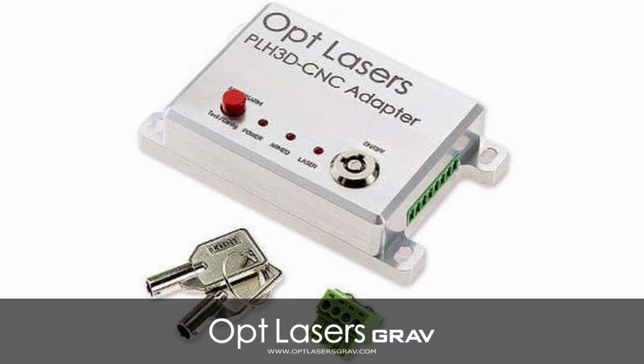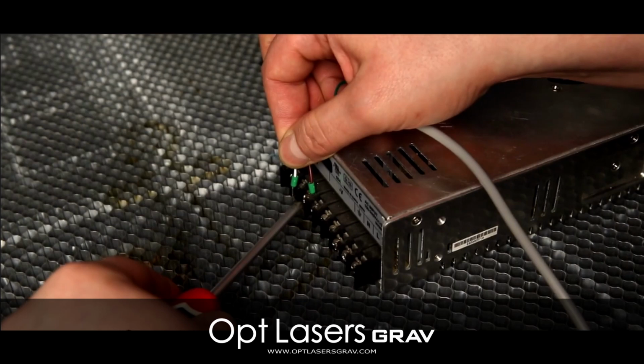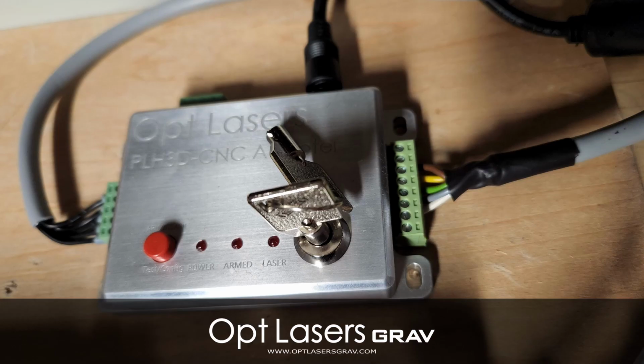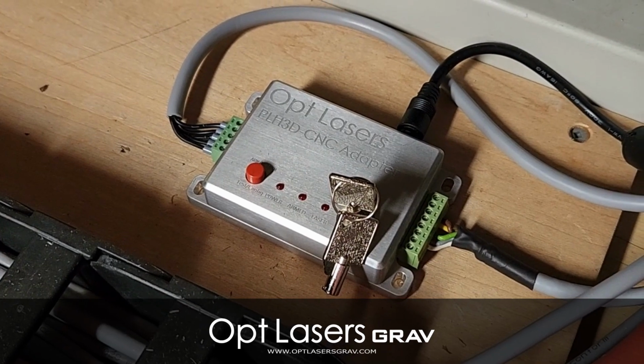Next, let's find the CNC adapter and get that installed. Every laser upgrade kit should come with a CNC adapter. You can choose not to use the CNC adapter or the safety features that are incorporated into this unit. The laser head gives you the option of direct integration. The wiring from the control box that has the 8-position connector will attach to this adapter. The adapter will arm and disarm the laser head.